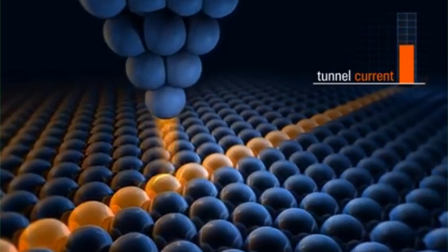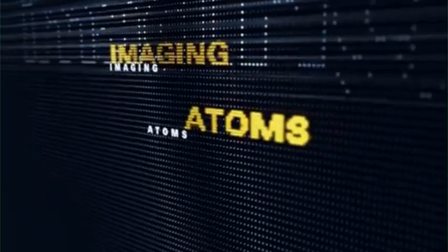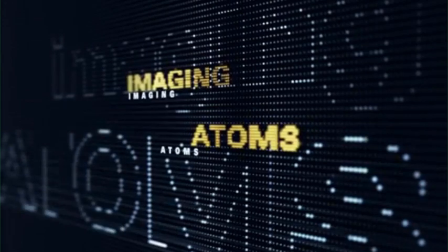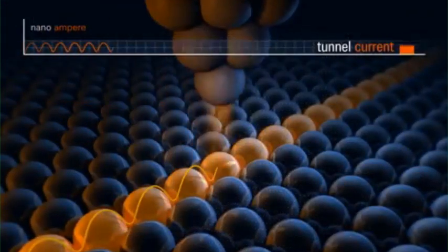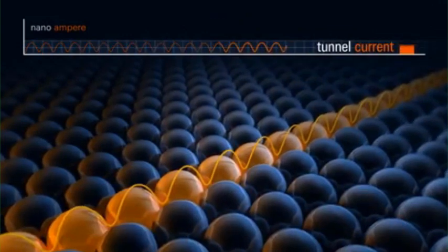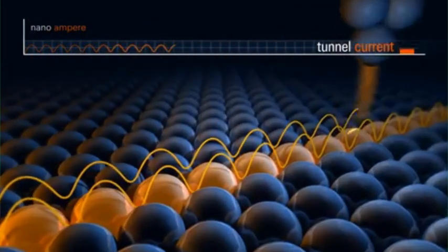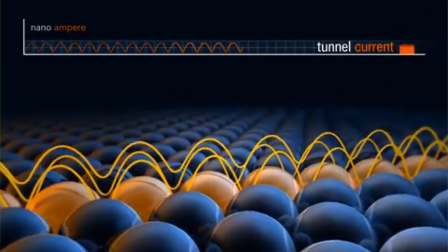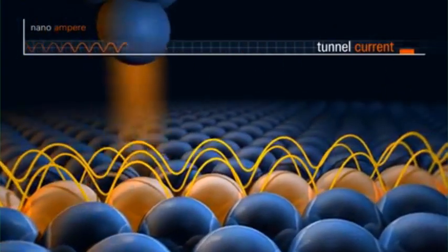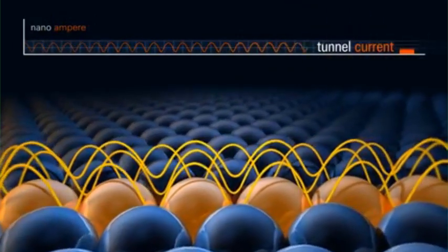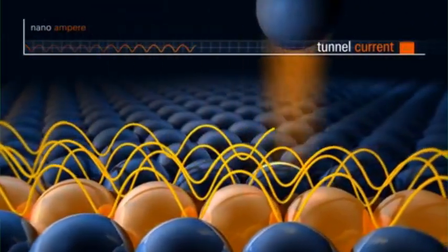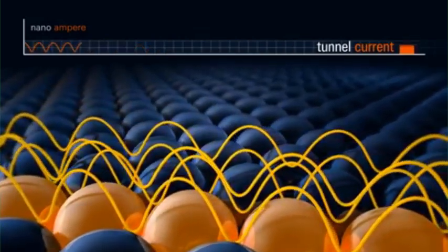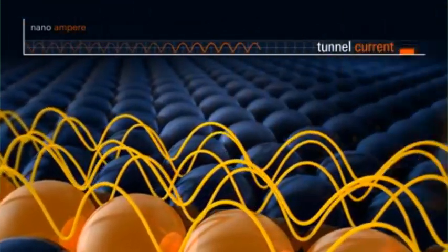Scanning probe microscopes employ a tiny probe with a very sharp tip that is brought into very close proximity, i.e., to within on the order of a nanometer, of the specimen surface. This probe is then raised or scanned across the plane of the surface. During scanning, the probe experiences deflections perpendicular to this plane in response to electronic or other interactions between the probe and specimen surface. The in-surface plane and out-of-plane motions of the probe are controlled by piezoelectric ceramic components that have nanometer resolutions. Furthermore, these probe movements are monitored electronically and transferred to and stored in a computer, which then generates